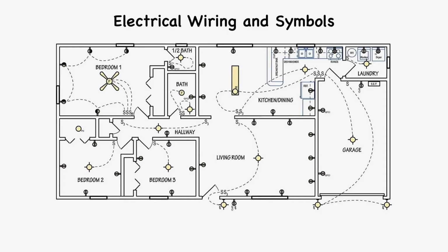Electrical symbols are used on home electrical wiring plans in order to show the location, control points, and types of electrical devices required at those locations. These symbols, which are drawn on the floor plan, show lighting outlets, receptacle outlets, special purpose outlets, fan outlets, and switches. Dashed lines are used between symbols to denote which switches control specific lights or receptacles.